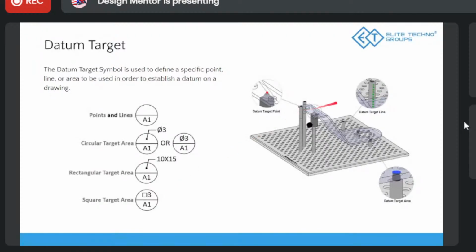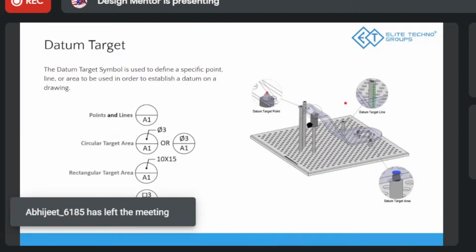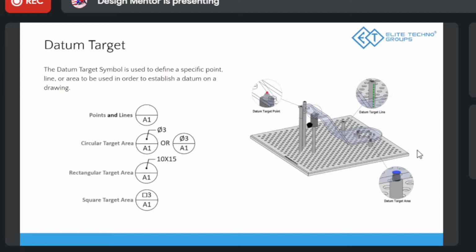And then you also have target lines. Whatever these three lines are, these 1, 2, and 3 are able to hold the part in a particular position. It won't allow the part to go elsewhere. So the part is rested down, and it's also rested here and here, like at the back also. Then you can start and figure out where the part is. Then you can start and measure if it's correct or not, if the angles and the curves and everything are right or not.